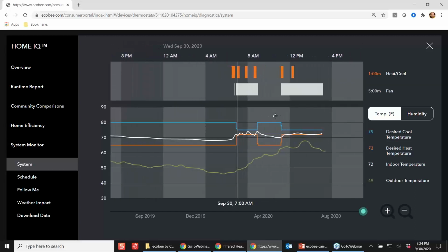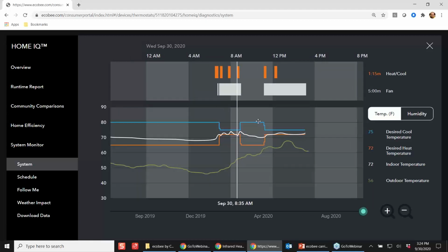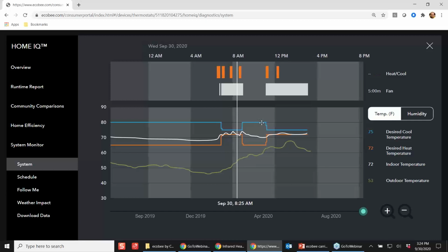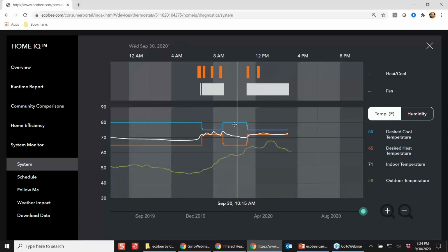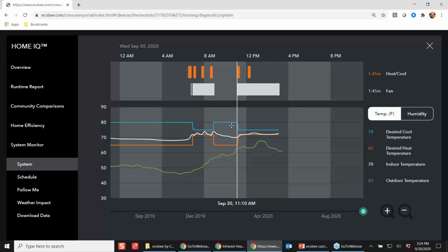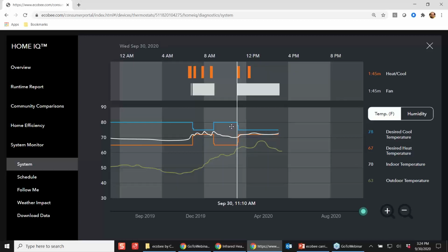So for this particular location, it knows to run occupied mode, which includes the fan in my case, every day from 7 a.m. to 9 a.m. It always does that. And then if I happen to show up at this particular building, I usually don't because I'm usually over at Melrose teaching a class. If I'm in this building, then it would know that I'm here and it would keep running. In this case, I came from somewhere else. I came here at, I think it was like 10:45 or whatever. So after like 15, 20 minutes, it realized I was here and it went into the occupied mode.